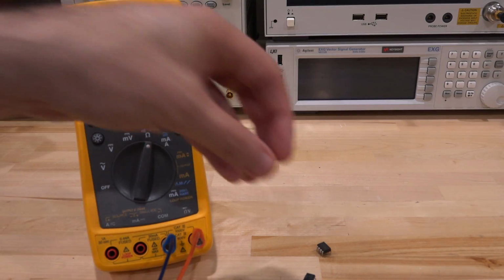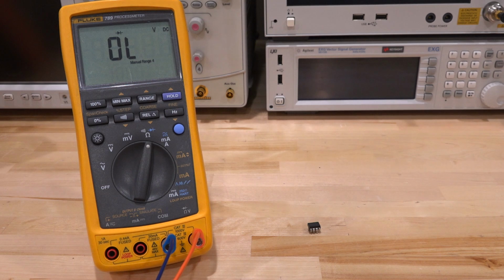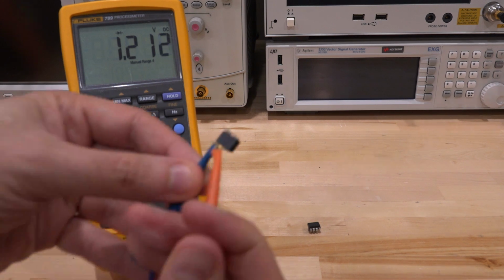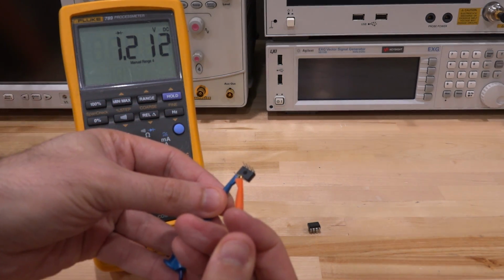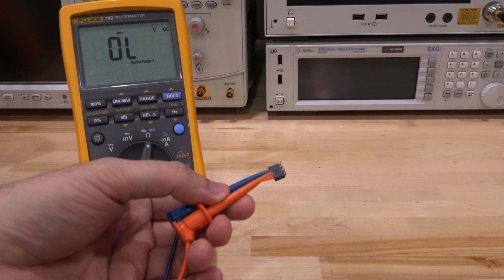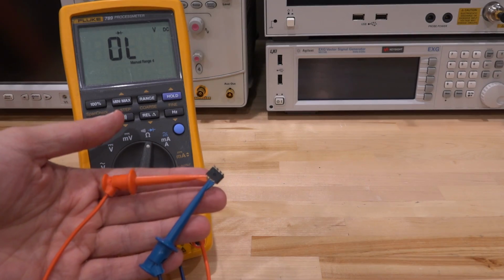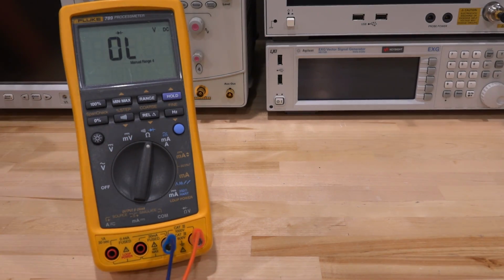So let's go ahead and measure these optoisolators relative to each other. This is the one that I took out of the unit, and this is a brand new one. So let's measure the brand new one. First thing I'm going to do is measure the forward bias voltage of the built-in LED and see how much that comes out as. There you go. You can see I'm connecting it to pin 2 and 3, and it has a 1.2 volt forward bias voltage. Now we can repeat this exact same situation for this one and see if we get similar voltages at all. What do we get? We get nothing. Yep, this is indeed an open circuit. I can flip it the other way too, just to be on the safe side. Yeah, there's nothing. So that makes sense. The LED is broken.